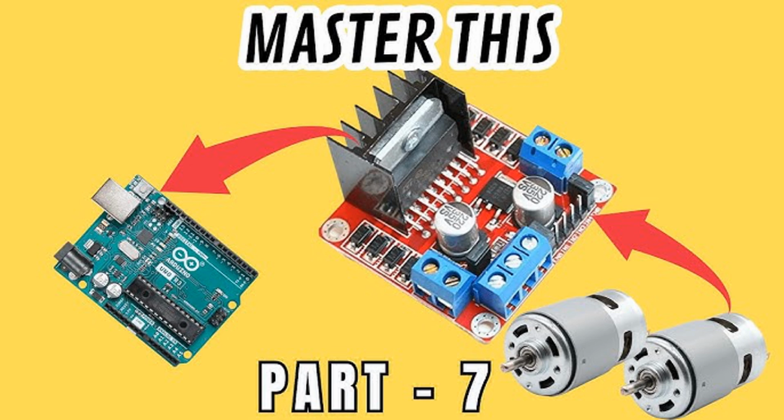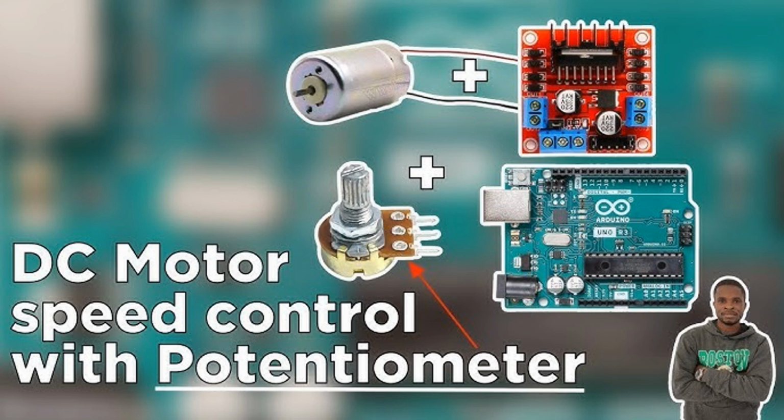4. Current limiting drivers. Function: Protects the motor and circuit by limiting the current to a safe range. Operation: By incorporating current sensing circuits, these drivers monitor the current flowing through the motor. If it exceeds a set threshold, the driver limits or shuts off the power to protect both the motor and driver circuitry. Applications: Used in applications where sudden changes in load could cause current spikes, like in robotics or industrial machinery.